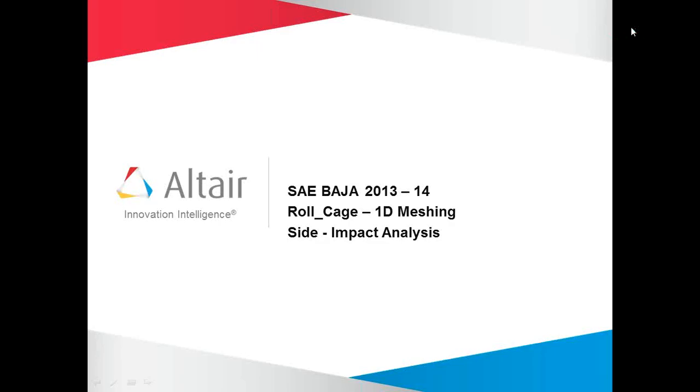In this video I am going to cover how to perform 1D meshing and side impact analysis. I have a line CAD model in which the line geometry is there. Then I will show you how to create 1D meshing or 1D elements on this line data of a roll case structure. And then we will also see how to simulate side impact analysis using Radioss and HyperMesh. Then we post-process our result, that is, we will view our results of displacement and stress and animation plot due to the side impact in HyperView.